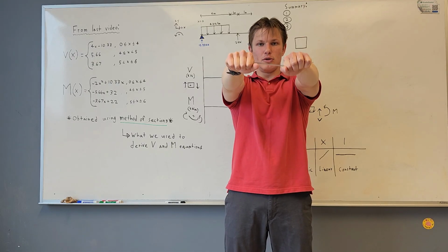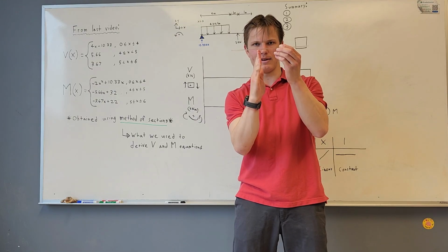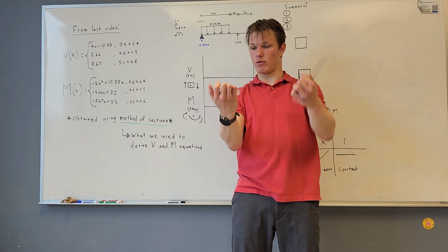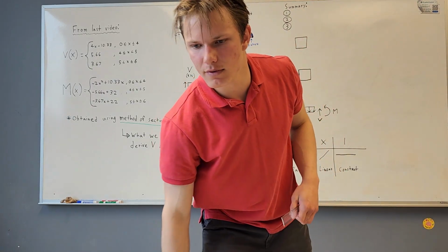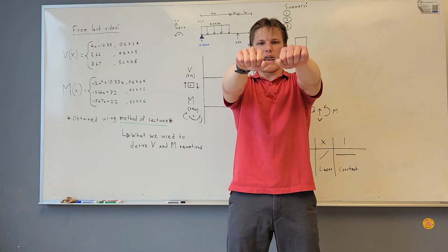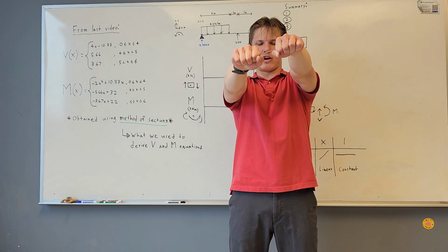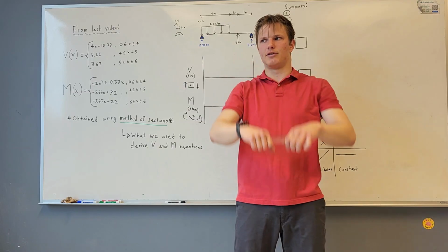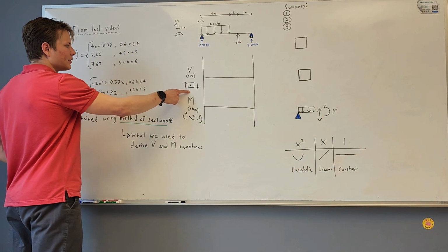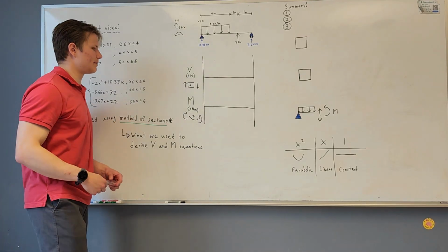And so these are 2 different kinds of shear because I'm applying forces perpendicular to this beam. But in one case, the forces, wow, I guess I exceeded the material strength. But when I apply that shear, I will either get forces that are being applied in a clockwise or counterclockwise direction. And typically, we will use clockwise as our main sign convention for when we're drawing these diagrams.